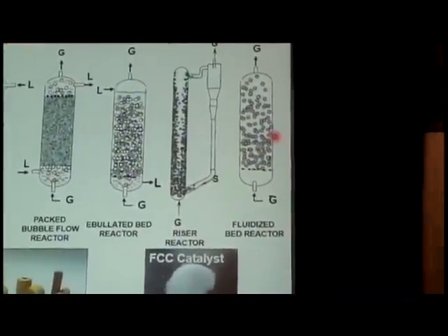And of course, also the conventional fluid bed reactor, which doesn't involve circulation of the solids as it does in the moving bed. Of course, in this moving bed, in particular the riser, we often operate in a turbulent flow regime where the particles can undergo significant attrition if we don't have a particle designed with the appropriate type of attrition resistance. So the science of catalyst technology in all these processes is very important.